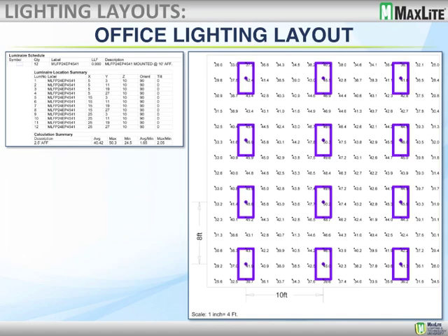Light loss factor takes into consideration, when it was a fluorescent fixture or an HID fixture, the lamp depreciation and the dirt depreciation, and you multiply those together. On a fluorescent fixture in an interior, you're usually about a 0.81 light loss factor. So the light loss factor takes into consideration the amount of illumination you're getting down the road, not initially. If you want an initial foot-candle, what you're going to get right out of the box, you put the fixtures at 1.0, which is no light loss factor. So that is where it goes to 0.9, which is what we're taking for dirt depreciation.